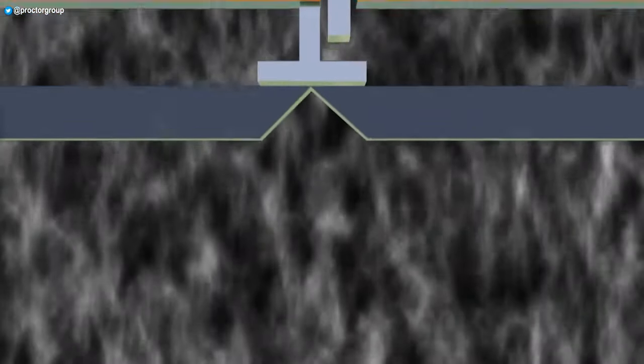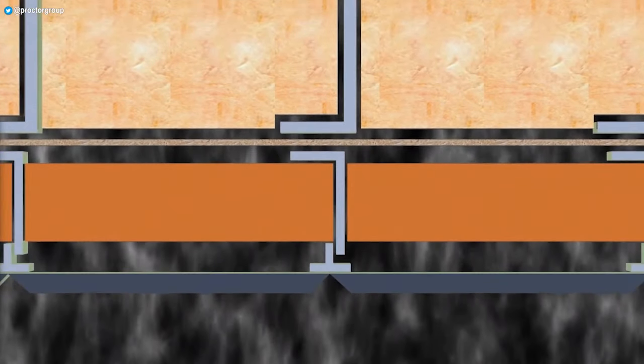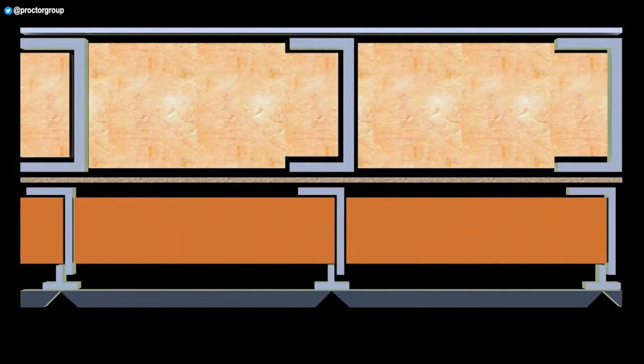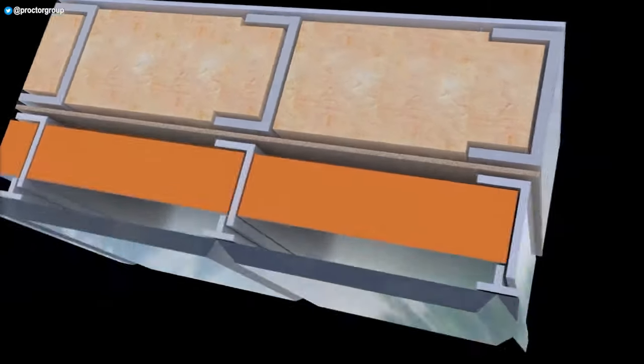Transfer by convection occurs when airflow acts as a transport mechanism, carrying moisture in or out of buildings. Holes, cracks, penetrations and leaky ductwork may all provide potential pathways for moisture movement. As the moisture passes through the building, it will condense on surfaces with temperatures that are below dew point. Condensation levels will be affected by the difference of temperature between inside and outside, relative humidity and the speed of air movement.